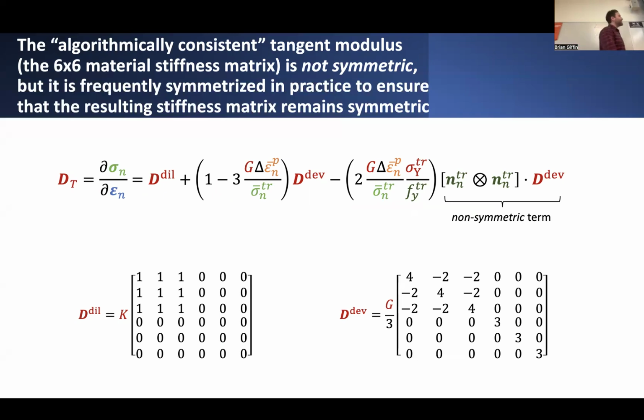Now, obviously, it'll be different depending on whether or not there's plasticity going on, and I've factored that into exactly these expressions. But the other thing that I want to point out about this ensuing expression for the tangent modulus, in the case of a multi-axial plasticity model, applying this same elastic predictor, plastic corrector, radial return concept, unfortunately, even though we had formulated our elastic tangent modulus to always be a nice symmetric 6x6 matrix, in the case of plasticity, we actually lose that symmetric behavior.